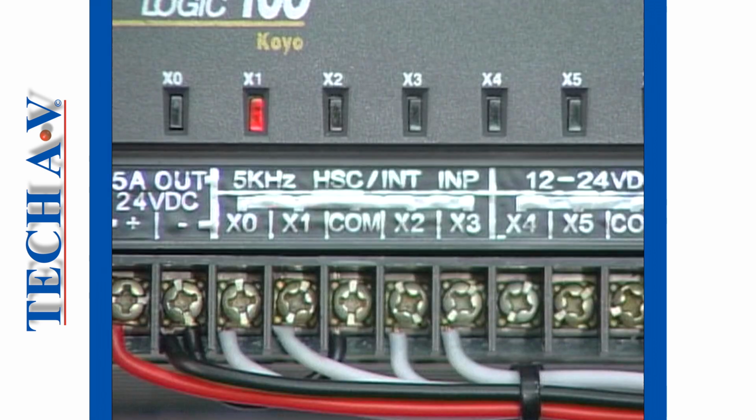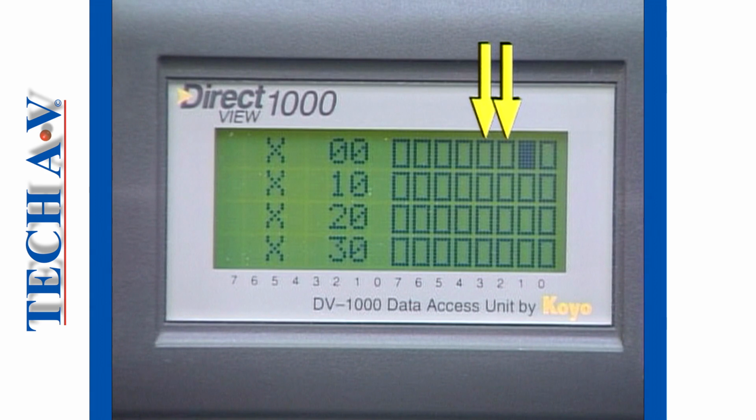The block activates both limit switches, sending an on voltage signal to inputs X2 and X3. On its next scan, the processor checks the status of each input address location and updates the input register with the latest information from these two external input devices.